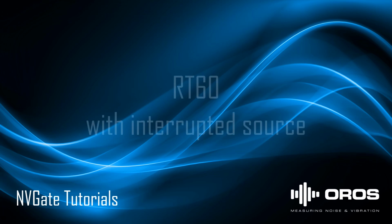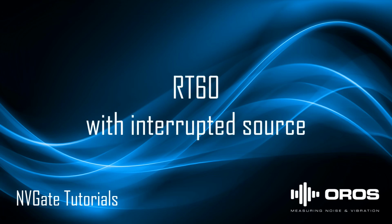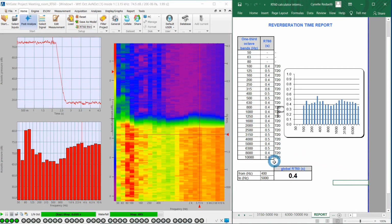Thank you for taking the time to watch this tutorial video on the use of RT60 with interrupted source. RT60, or reverberation time, is used for room and building acoustics and sound power measurements to characterize a room. It corresponds to the time needed for sound to decrease 60 dB after the interruption of the noise source or after an impulse noise, like a gunshot.